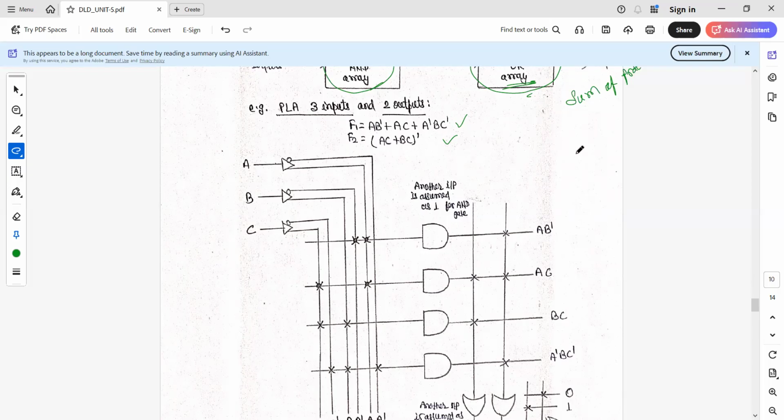In that case, when we take the K-maps, we have to see that both K-maps have maximum overlap for minterms, either by using the complement or if it is directly available, then it's okay. Otherwise, we have to take the complement of one function so that we have a limited number of product terms as per the given specification. So here, in this case, we have 4 unique product terms.